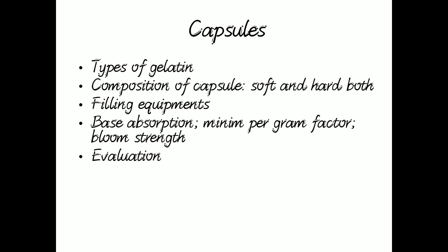The main steps are the filling and then finishing, followed by the dusting or polishing step. It can be like salt polishing, cloth polishing, brushing, dusting, and inspection is the final step, which is done to pick up the imperfect or damaged capsules. For that purpose, Rota Sort is a sorting machine which is sold by Eli Lilly company. Okay.